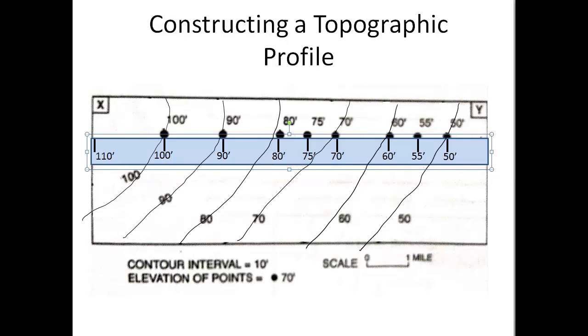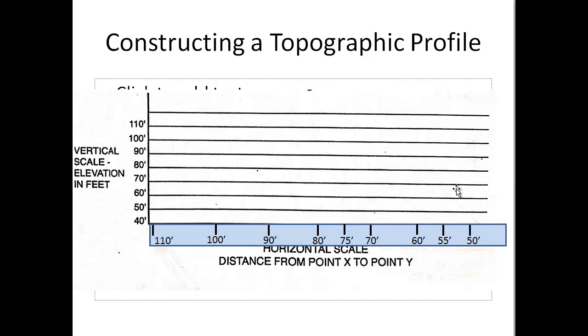field. So if we set up a simple graph and then establish a vertical scale to represent the land elevations. Any vertical scale will do, but usually this scale is going to be exaggerated and doesn't actually equal the horizontal scale. So we put this strip of paper with our marked elevations along the bottom of the graph, and then we'll draw a line up from each elevation mark on the strip until it intersects the line on the vertical scale that has that same elevation.